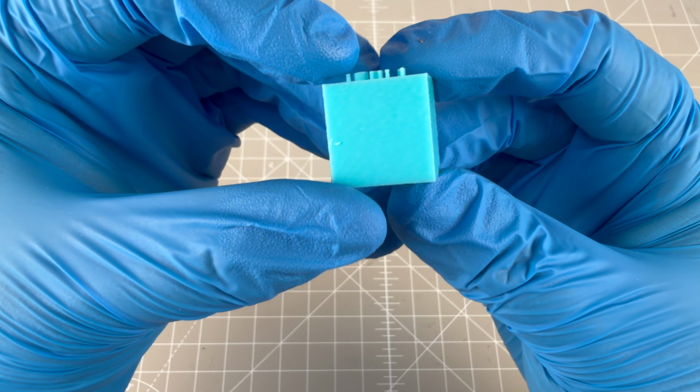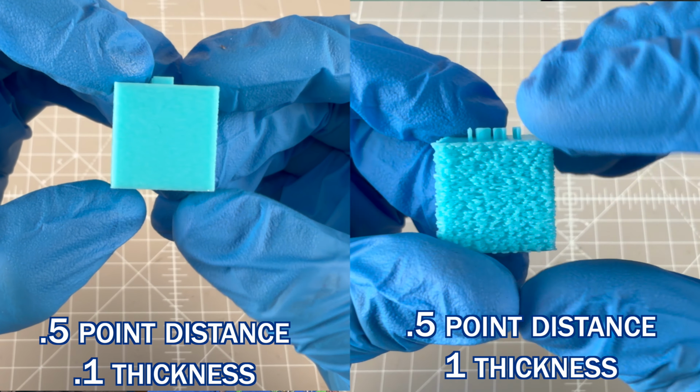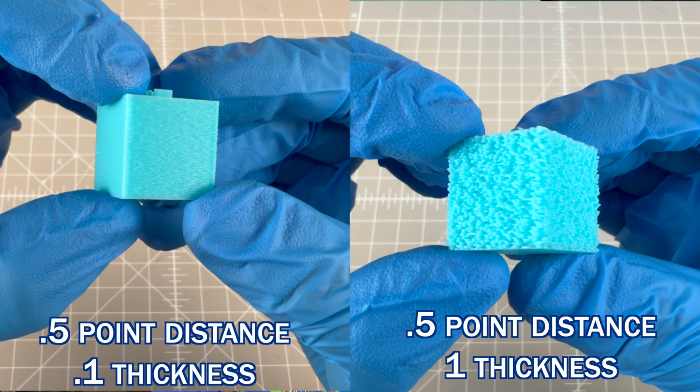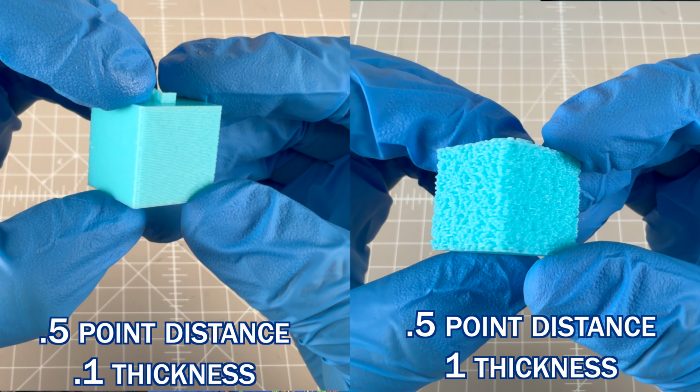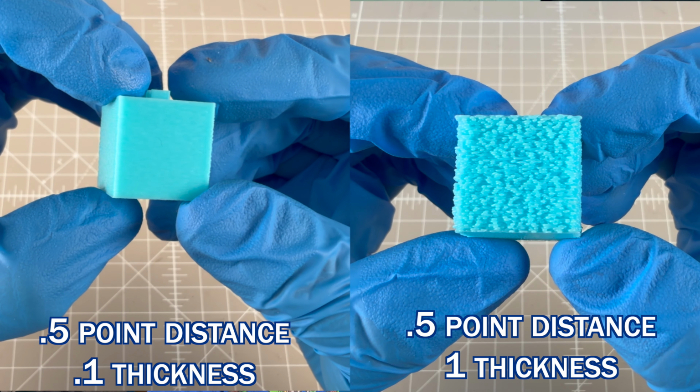Looking at the test cubes may also provide some clarity around what point distance and thickness are actually doing, assuming my incredibly impressive graphics didn't help, by comparing the highest and lowest settings of each without changing the other variable. Keeping a constant point distance of 0.5, the texture is not very pronounced when the thickness is 0.1. However, if we keep the point distance the same, we see that the bumps on the surface become much more pronounced as the thickness goes up. The distance between points is approximately the same, but the peaks and valleys get steeper as thickness increases.